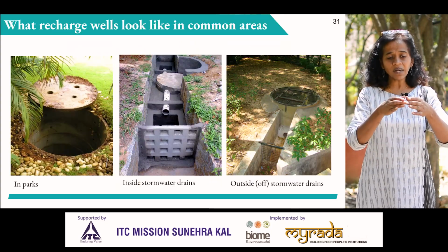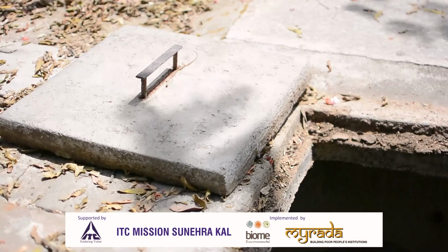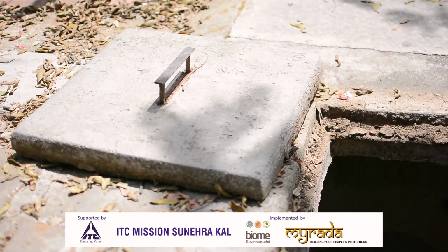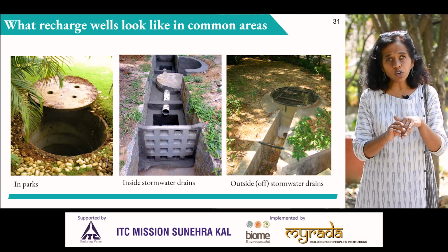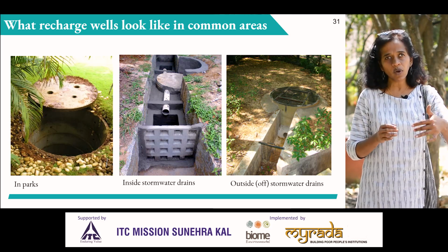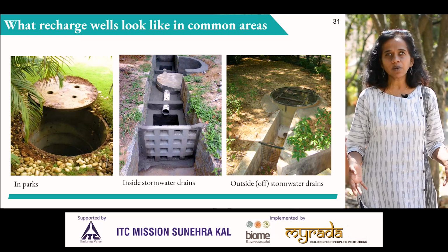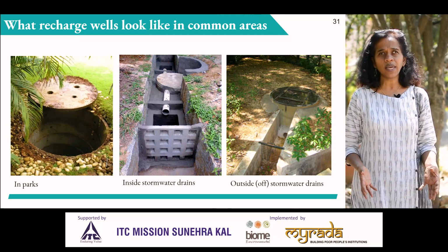Once the well is dug, on top, cover it with a concrete slab. Make sure the concrete slab has some kind of opening such that you're able to look into the well to see if water is going into the well, and to monitor the rate at which water is flowing out of the well as well.